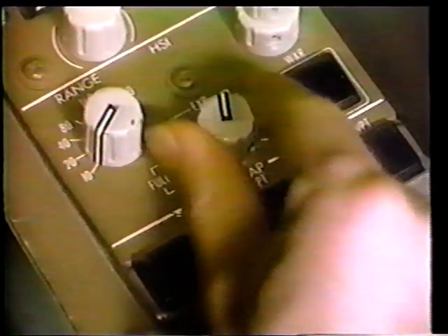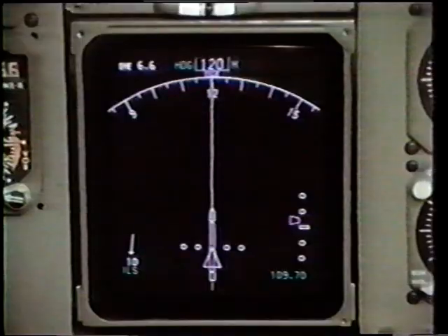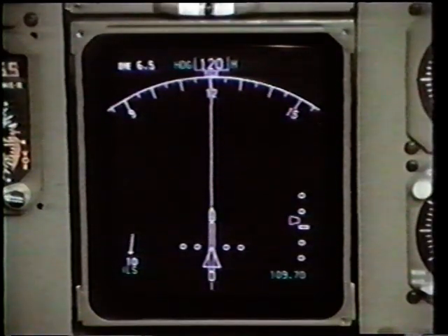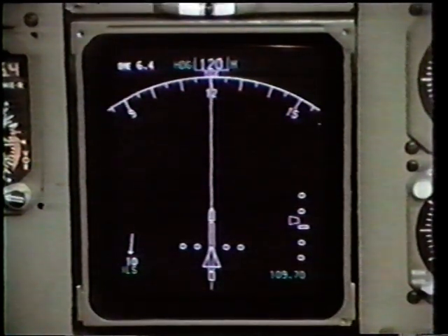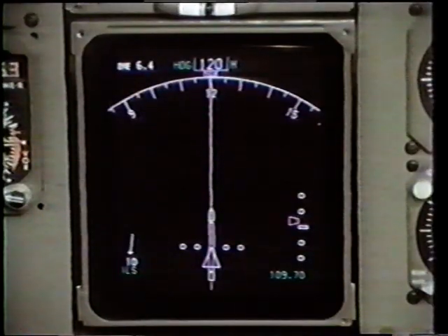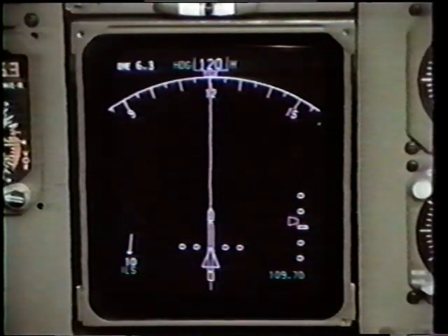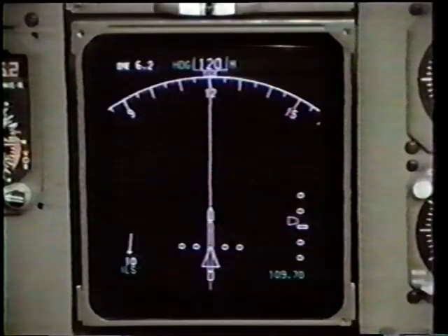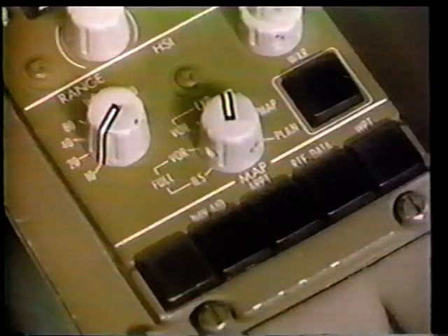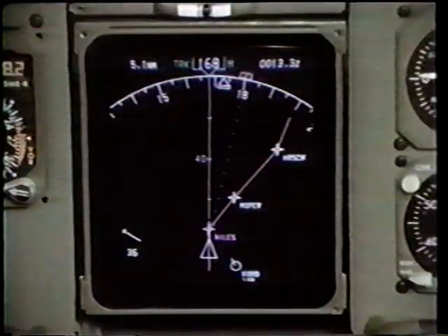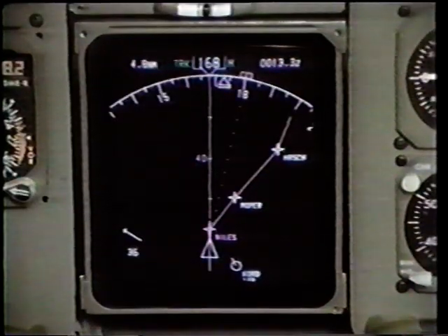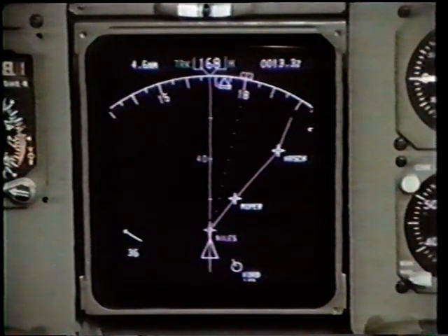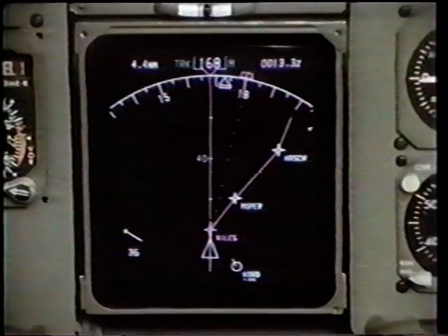In the expanded ILS mode, the display is almost identical to the VOR mode, but shows localizer course deviation. As in the full ILS mode, it also adds glide slope information on the lower right scale and tuned ILS frequency. The map mode aids the crew in maintaining a mental image of their flight path by presenting route information against a moving map background.